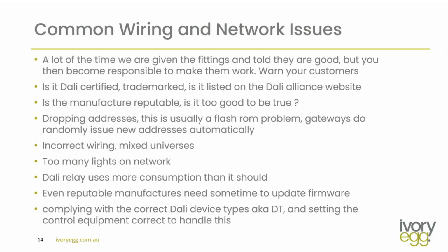I've seen instances where things like DALI devices that are not certified, and DALI relays, consume more on the DALI bus than is allowable, and this can create a problem. It can overstress the power supplies and max out the current consumption beyond what it should. So keep a lookout for things like that. I've talked about this before.